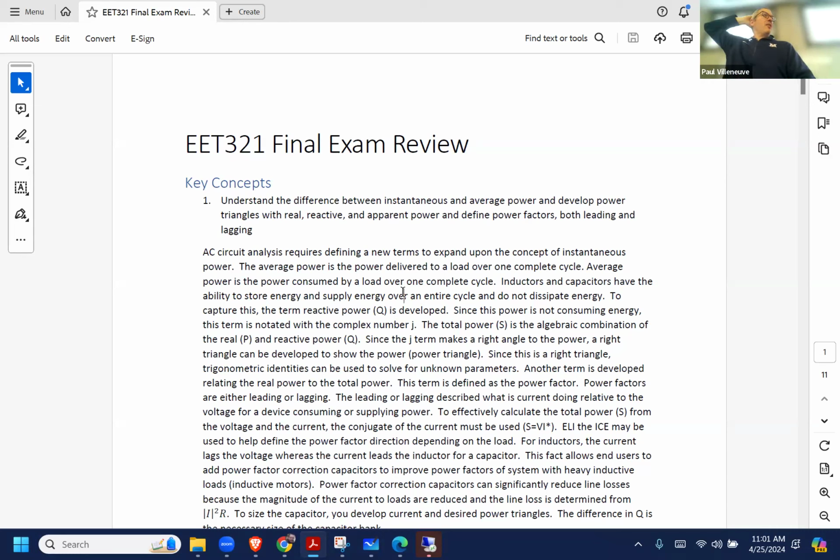With voltage and current, we can't use average voltages and currents because over one sine wave, the average voltage and current would be zero. So we use the concept of an RMS, which is a way of taking that negative value and flipping it around. And then that whole square root of 2 stuff that we developed is all based on making our power equations work correctly. If we're looking at a purely resistive load, we want P to be equal to V times I. Well, if we did v(t) and i(t) and multiplied it out, we'd have to divide the magnitudes of the voltage and current by 2. So what we do is we distribute the 2 into 2 square root of 2s, and then we divide each one individually, and that's where we come up with the RMS quantities.